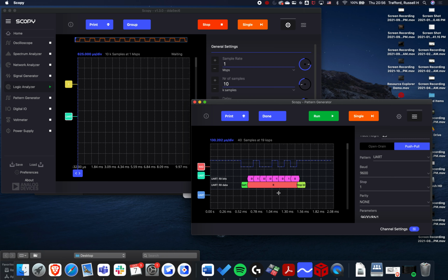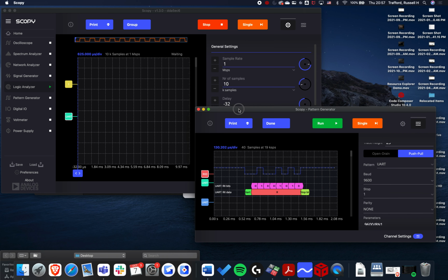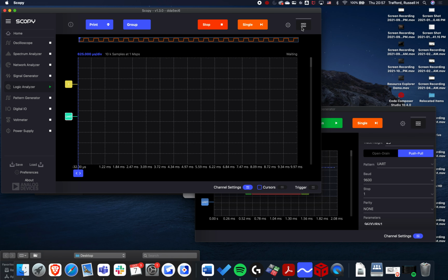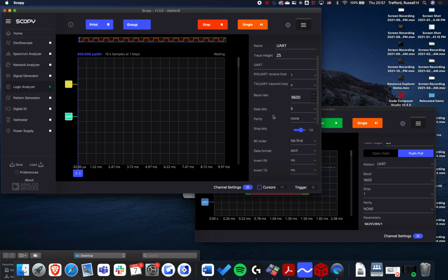And I've configured it such that one of the pins is going to go onto the receive, and one of the other pins is listening to transmit. So on the window on the right here, I have what I'm going to send to the MSP430, and on the left here I have TXD, which is basically what we are receiving. And I've told it already that I want to listen out for a UART type protocol, and I want you to try and decode it.